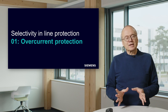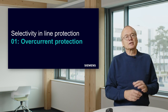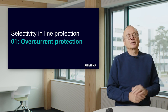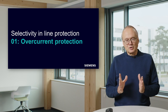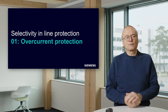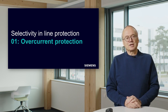And this has to be dealt with in a different way for our three different short circuit detection functions: differential protection, distance protection, overcurrent protection. For differential protection it is pretty easy because this principle is by itself selective. That means this reacts only if there is a fault on a protected device. That means in the context of selectivity, that is pretty easy.